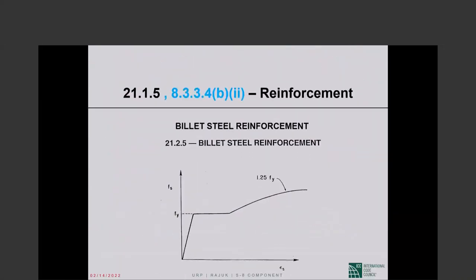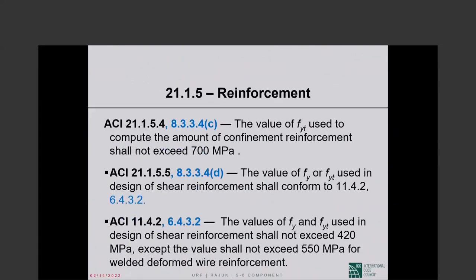The third of three supplementary requirements is that the actual tensile strength shall be no lower than 125% of the actual yield strength when tested. And I explained to you why, and I will not go into that a second time.